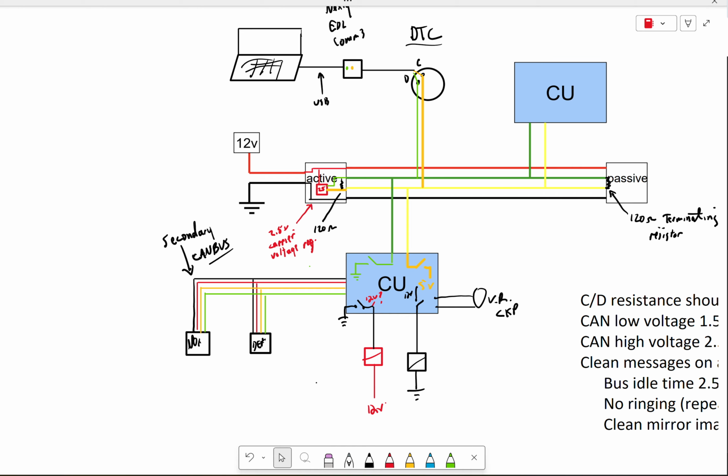If you have things like, let's say a hydraulic valve stack, where you have all of those individual little electronic control modules mounted right to each valve spool, all those ones are doing is just running on their own little CAN that runs off of the main hydraulic controller, right? So in a lot of modern equipment, it's very, very normal to have multiple CAN bus networks. And one of the biggest reasons for that is making sure that we don't overload the main CAN bus network, okay? There's different CAN bus networks operating at different speeds as well. That's another thing to consider.